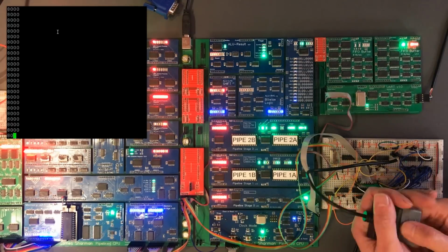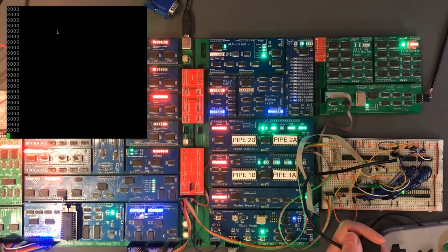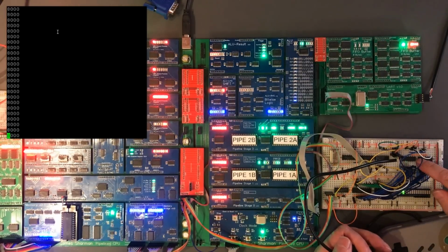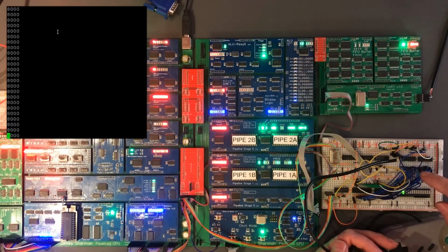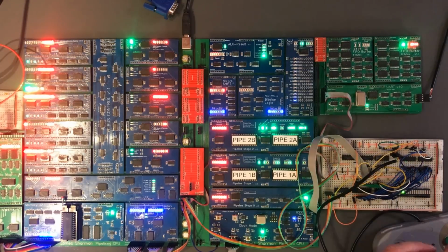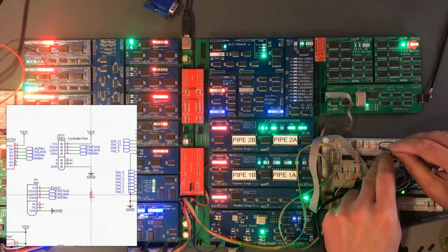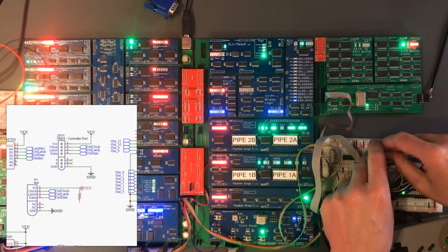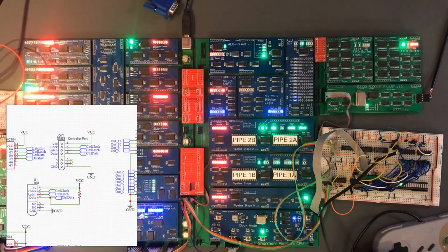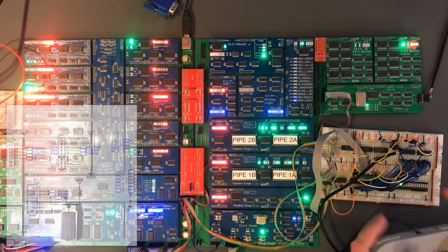Something I want to check is what happens if I unplug the controller. Right, that kind of works. I think the shift register we've got here has an internal pull-up, and because we invert the data returned from here, it's going to work okay, but I don't like that. With the connector unplugged, we effectively have a floating input to this inverter. So let's just stick a pull-up resistor on that, and then that makes us a little bit safer. And that shouldn't interfere with the operation of this circuit.